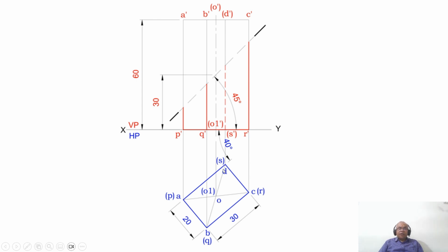Then by using the compass, you take any length and from there, you cut an arc on that 40 degree inclined line and mark that point. So here, you mark this as A and this as D. Through A, with reference to line AD, you measure an angle of 90 degrees using the protractor and draw a perpendicular line to this inclined line AD.